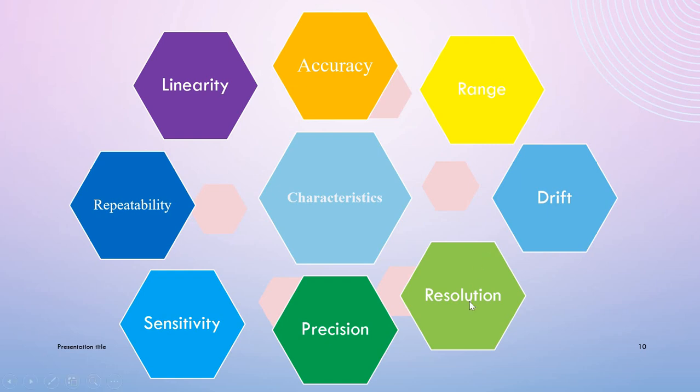And the next one is the resolution. Resolution is the smallest change a sensor can detect in the quantity that it is measuring. The resolution of a sensor with a digital output is usually the smallest resolution the digital output is capable of processing.